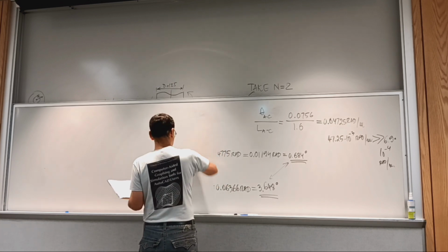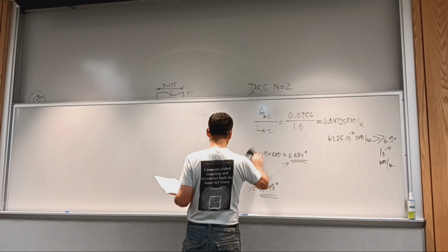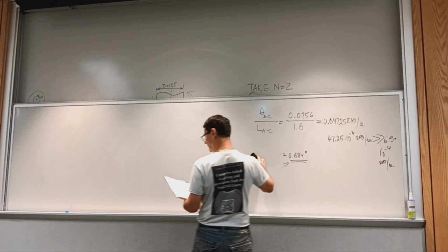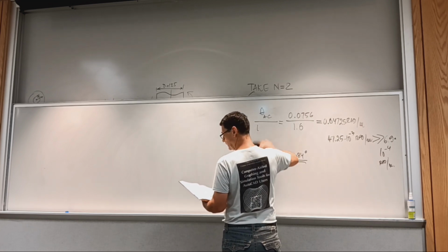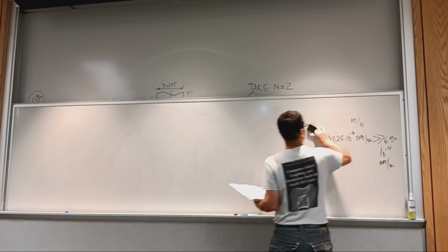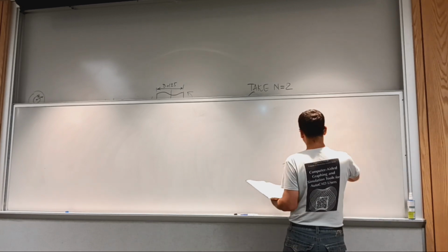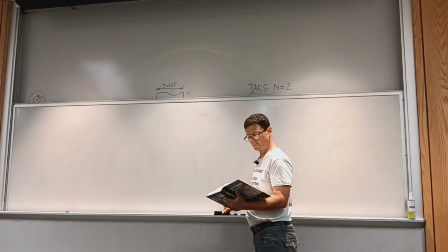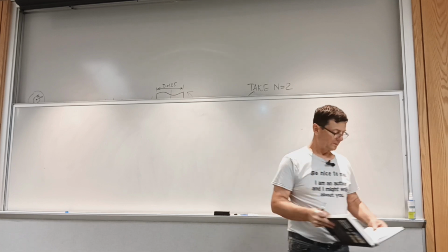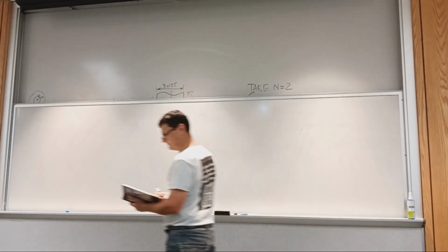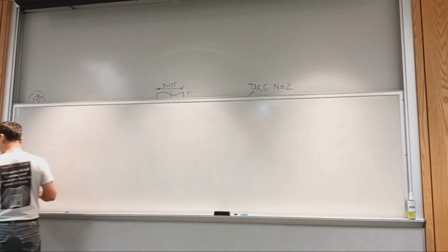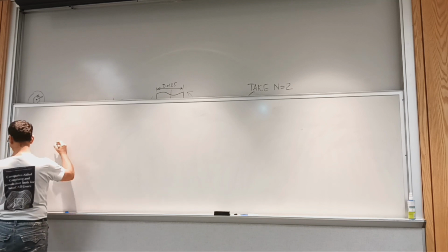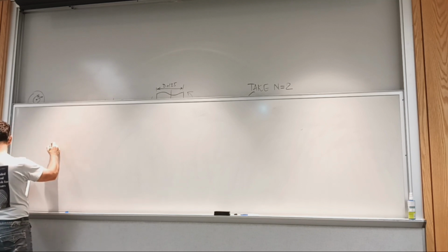It's a bell crank there, it's called. And then we need to calculate the shear stress upon the pin. So it's in single shear, not double shear. So in order to get the shear force, we have to find the reaction at the pin. And it's a lot of geometry there.